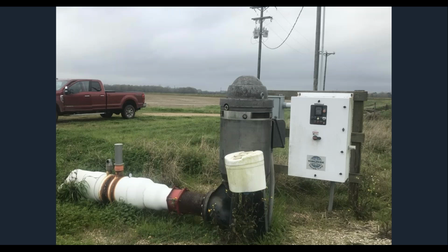Next slide, please. Here we have a vertical direct drive motor that was probably used on a new well where there was not an existing gearhead or shaft. And the only drawback to a direct drive motor is if you don't want to produce the maximum output on the well, there's no way that you can reduce the shaft speed because it's directly driven to the pump. Next slide, please.